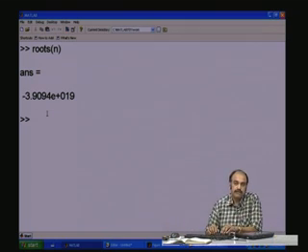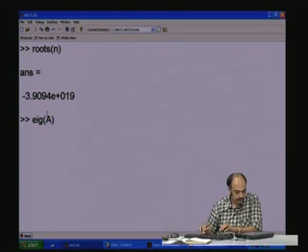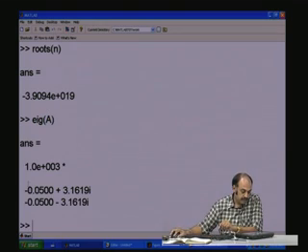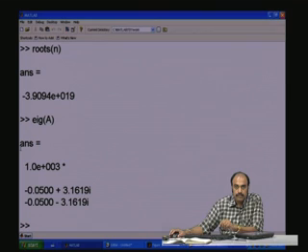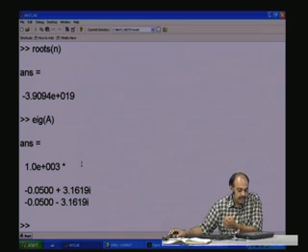The A matrix contains the information of the poles and zeros. Let us say you take the eigenvalue of A. Eigenvalue of A gives the pole location. So, basically the roots of the denominator of the transfer function are the same as the eigenvalues of the A matrix, which give you the poles. In fact, that defines the dynamics of the system, of any system for that matter. We can get any output to any input, as I was saying before.